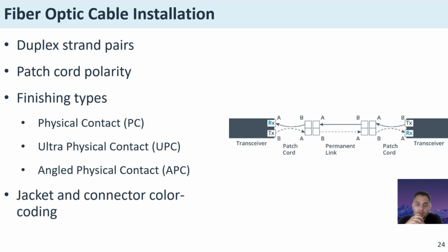These connectors are usually deployed when the fiber is being used to carry analog signal, as in cable access TV, CCTV, CATV networks. They are also increasingly used for long-distance transmission and for passive optical networks, PON, such as those used to implement fiber to the X, FTTx, multiple subscriber networks.